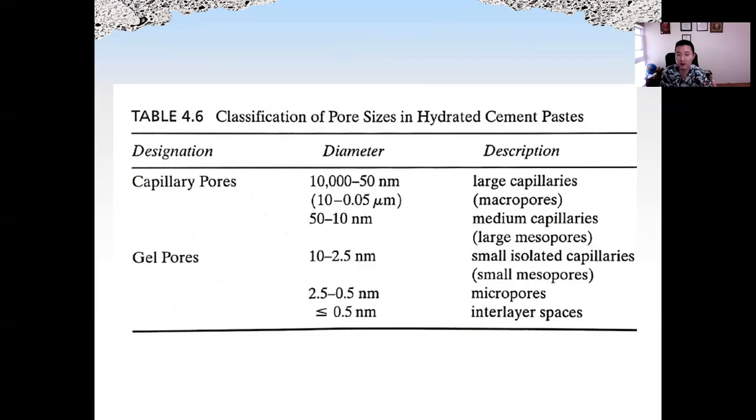The water in different types of voids, depending on the size, behaves totally differently on concrete when it evaporates. And we know concrete is a very brittle material. Too much shrinkage and the concrete will crack. That's the reason we care about the different types of voids.